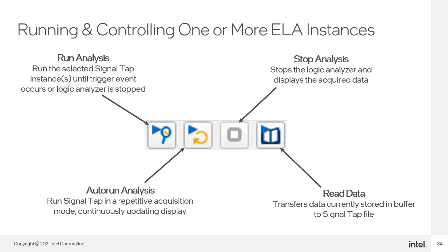When describing the operation of a logic analyzer, the terms run or running are often used. Running the logic analyzer means to start its monitoring of trigger-enabled signals, looking for the combination of signal states that satisfy the trigger conditions. This is also sometimes referred to as arming the logic analyzer, a term often used with external test equipment.